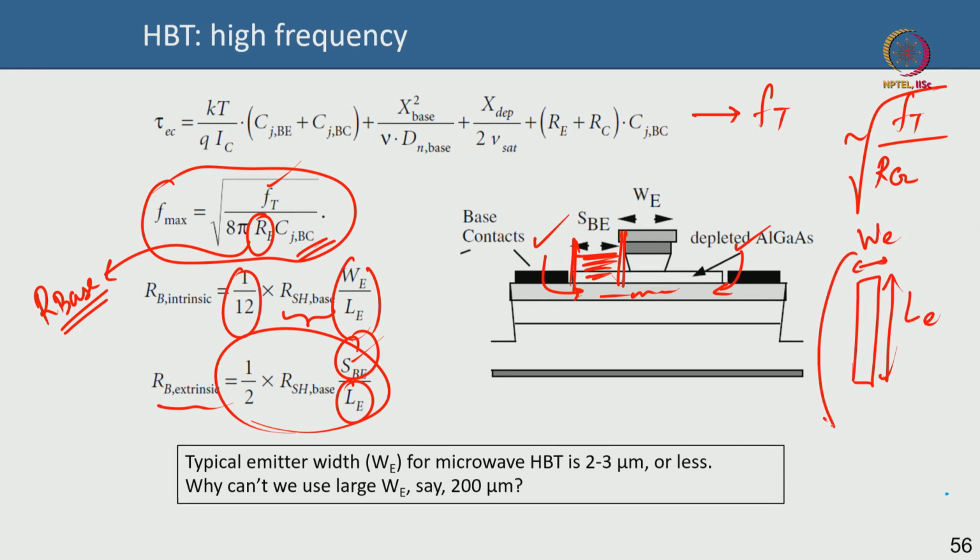So typically the width of the emitter, basically the nomenclature is that you have a certain process. Say if you say 0.13 micron CMOS process, it means that your width of the finger is actually 0.13 micron or 130 nanometer. Okay, and on this number the circuit designer does not have much control. You have to choose a different node like 90 nanometer, 130 nanometer. So this is not so much of a design parameter to the circuit designer. What he has control on is the length.